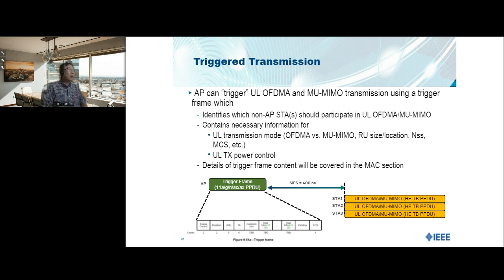Alfred will talk about that in the next section. From a PHY point of view, it will enable uplink OFDMA and uplink MU-MIMO, so multiple stations can transmit simultaneously.